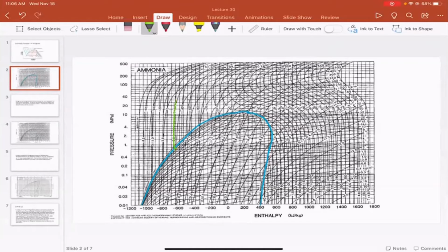And then we're going to go straight across here, and then we'll pick it up again right here. Okay, and that is one of the isotherms, at constant temperature. And there's a whole bunch of them. And you'll see that above the critical temperature, like here at 200 degrees, that one never touches the phase change regime, right? And that makes sense, right? If you're above the critical temperature.